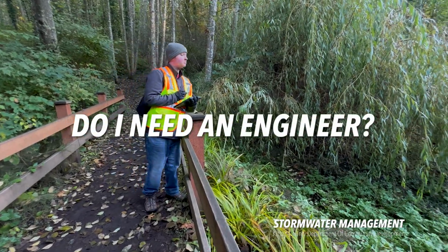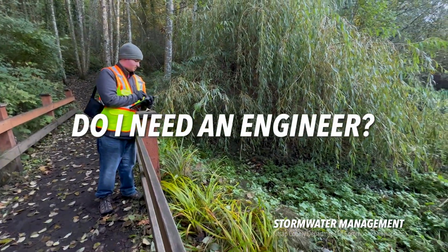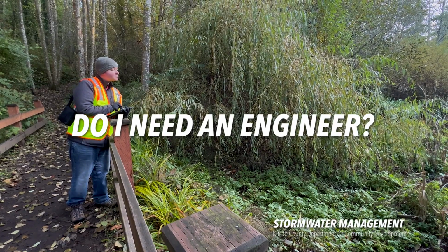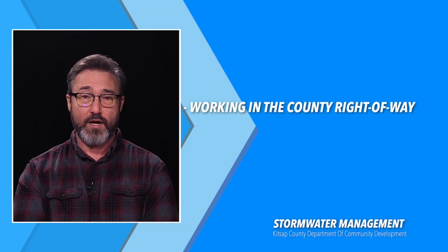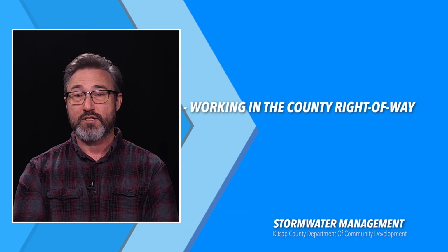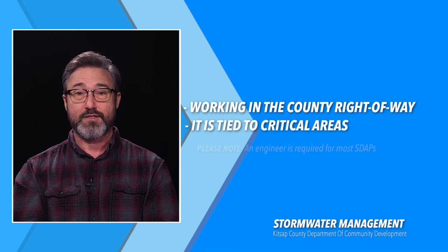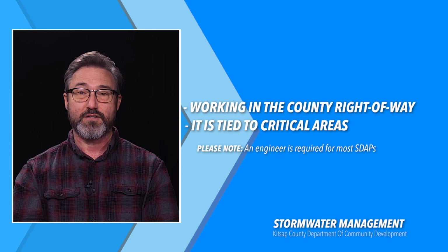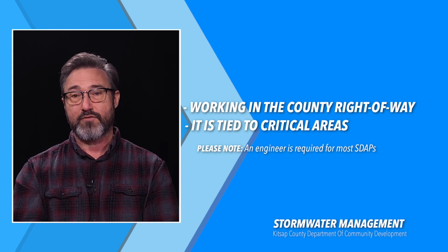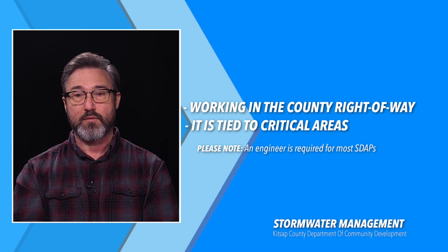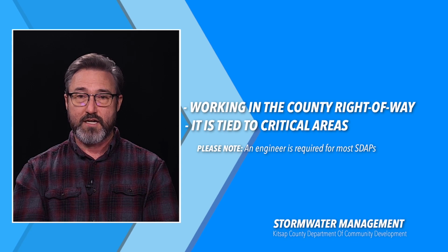Do I need an engineer? Having an engineer with your Site Development Activity Permit is not always required. Some reasons why working with an engineer would be necessary include the following. Working in the county right-of-way or connecting to a drainage system in the county right-of-way. It is tied to critical areas or critical drainage areas where there is a known lack of conveyance or movement downstream or other sensitive areas downstream.